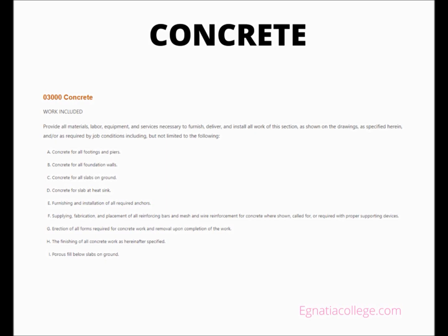Supplying fabrication and placement of all reinforcing bars and mesh and wire reinforcement for concrete where shown, called for, or required with proper supporting devices. Erection of all forms required for concrete work and removal upon completion of the work. The finishing of all concrete work as hereinafter specified. Porous fill below slabs on ground.